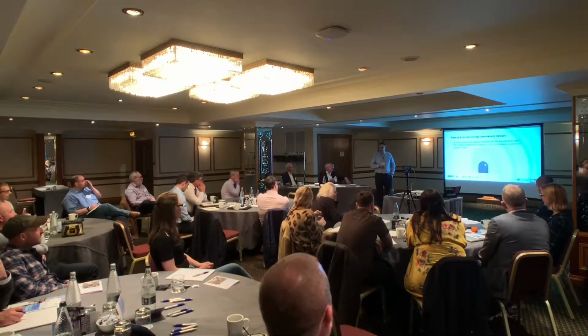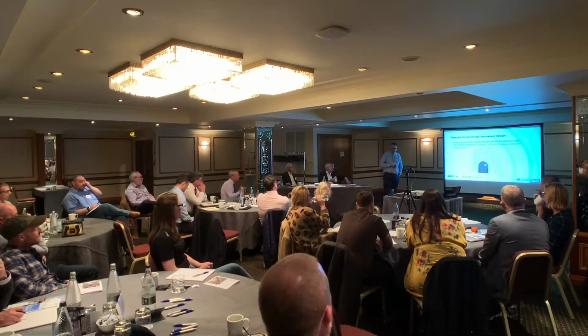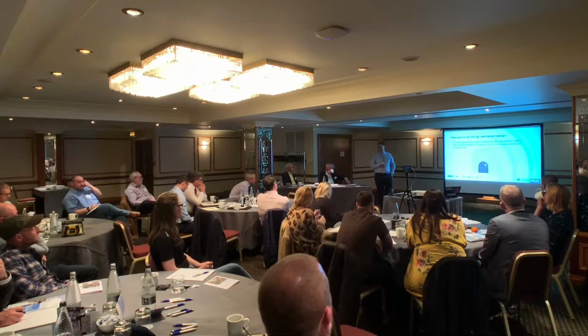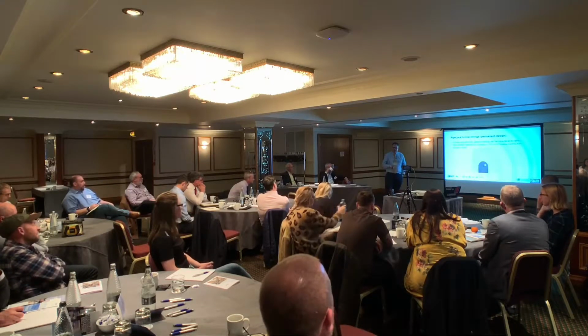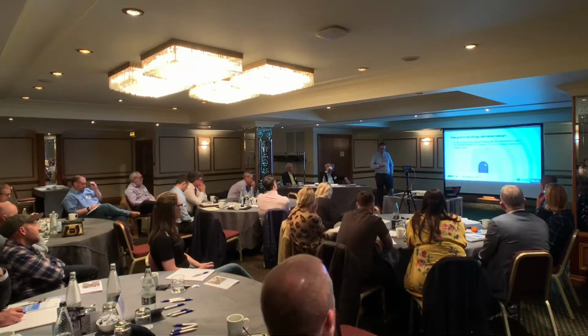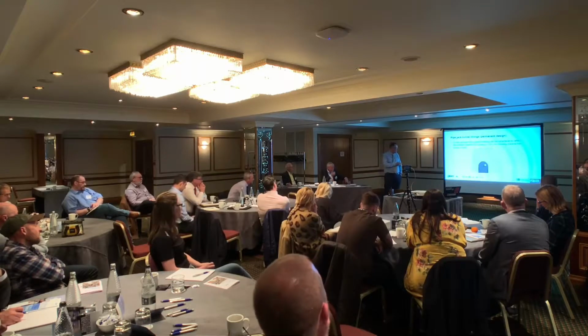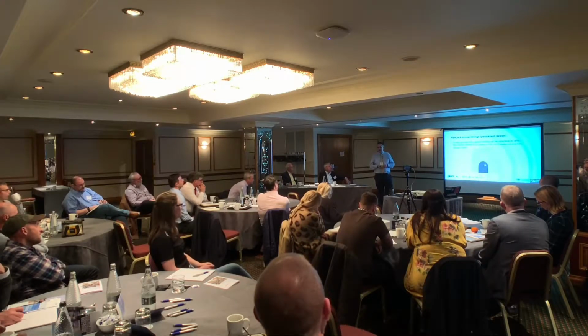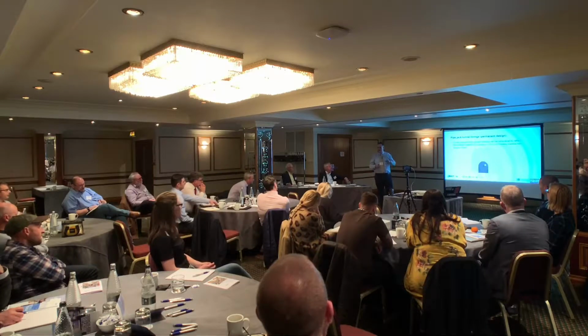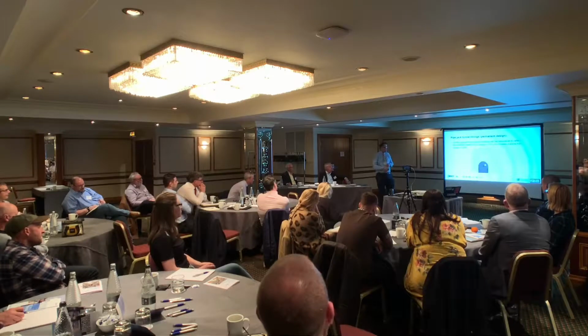Maybe in a loose sand and gravel, yes, and if you say at 5, 6, 7 meters deep, you could be picking up most of the load. But certainly, as you get deeper, the system needs to appreciate that you do get arching. I often say to people, when you try to explain soil arching, it's like doing something on a property at home: you can take so many bricks out of a wall, and the structure will arch over it, and you won't get any cracking. You'll get to a point where you take that many out, you need a lintel.